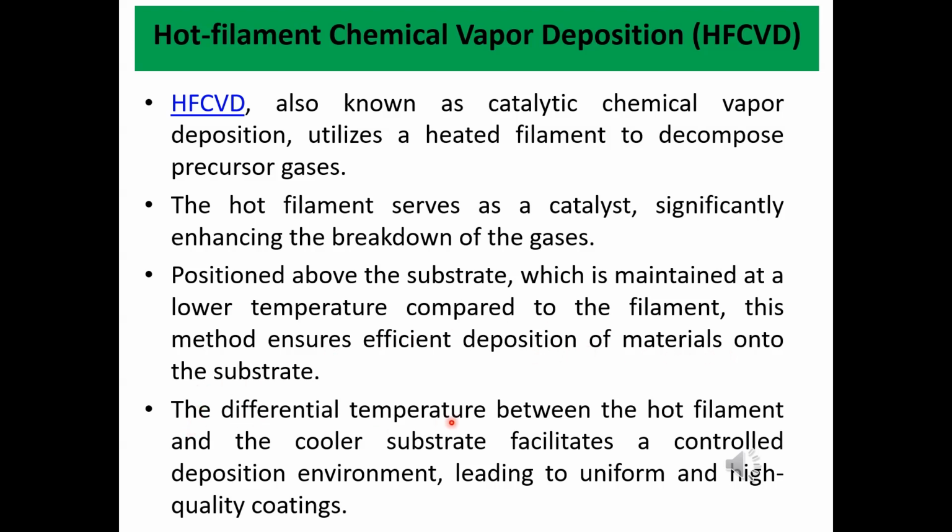The differential temperature between the hot filament and the cooler substrate facilitates a controlled deposition environment, leading to uniform and high quality coatings. So, the temperature gradient between the hot filament and comparatively cooler substrate facilitates a controlled deposition environment, and this controlled deposition environment gives us coatings and films of very high quality.